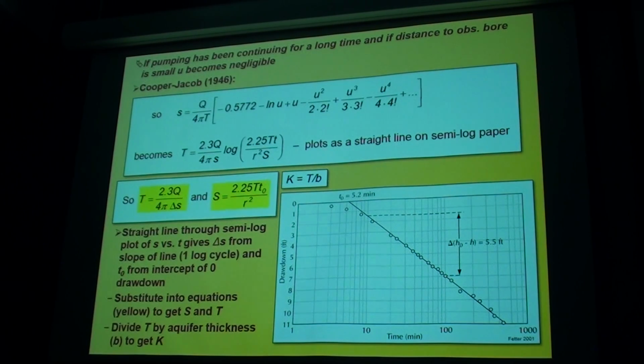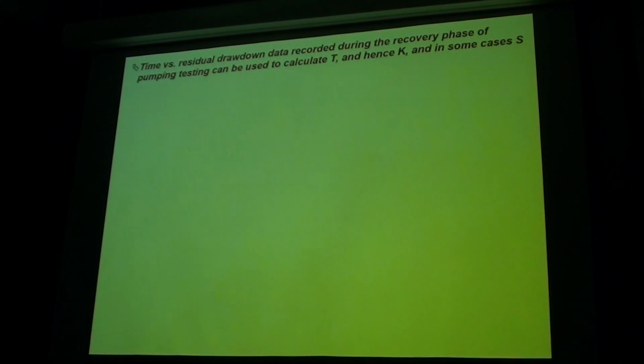Sometimes it's not that easy, because sometimes you drill 200 or 300 metres and get into an aquifer, and you have no idea how deep it's going to go. You can't go any further. It's quite a good aquifer, and you don't really need to go any further. So you don't actually know what b is. So sometimes establishing K can be really tricky. You've got to make some sort of estimate or guesstimate. But it's important that you establish some value of K because it's one of the most important parameters for the groundwater modelling, which I'll hopefully talk about in a minute.